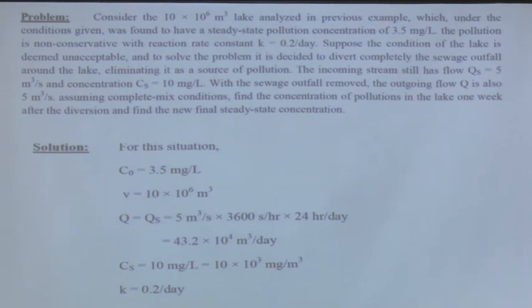How do I know? This calculation will tell you, but here I have to consider the rate of decay of the component. For this situation, C0, your initial concentration, is 3.5 mg per liter. The lake volume is 10 into 10 to the power 6 meter cube, and Q is equal to Qs, that is 5 meter cube per second multiplied by 3600 seconds per hour, multiplied by 24 for per day, because the question is for 7 days.